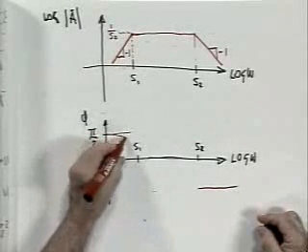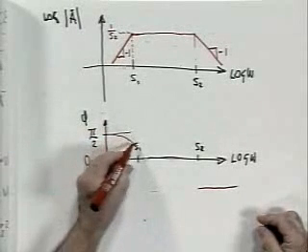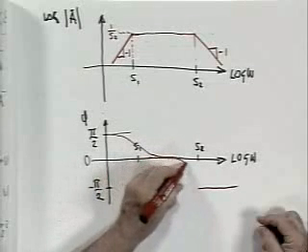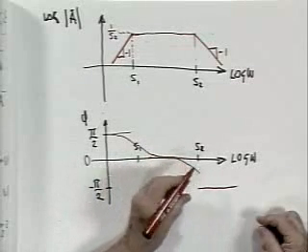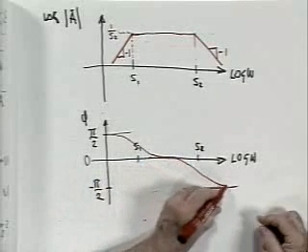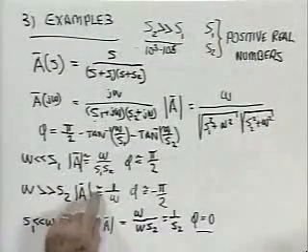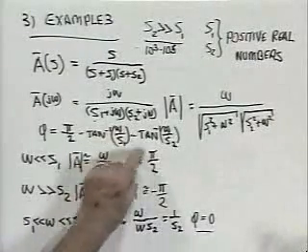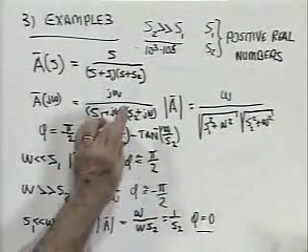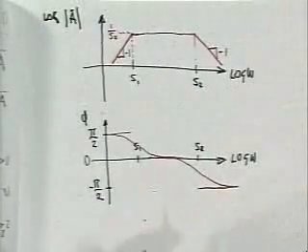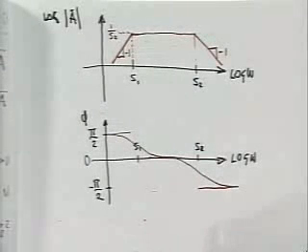It passes through 45 degrees at S1, approaches this, and then passing through minus 45 degrees there, comes back there. You can see the 45 degrees because when omega equals S1 or omega equals S2, the arguments here are unity, and the angle whose tangent is 1 is 45 degrees. Now, I haven't filled in all the details here, but you get the idea.